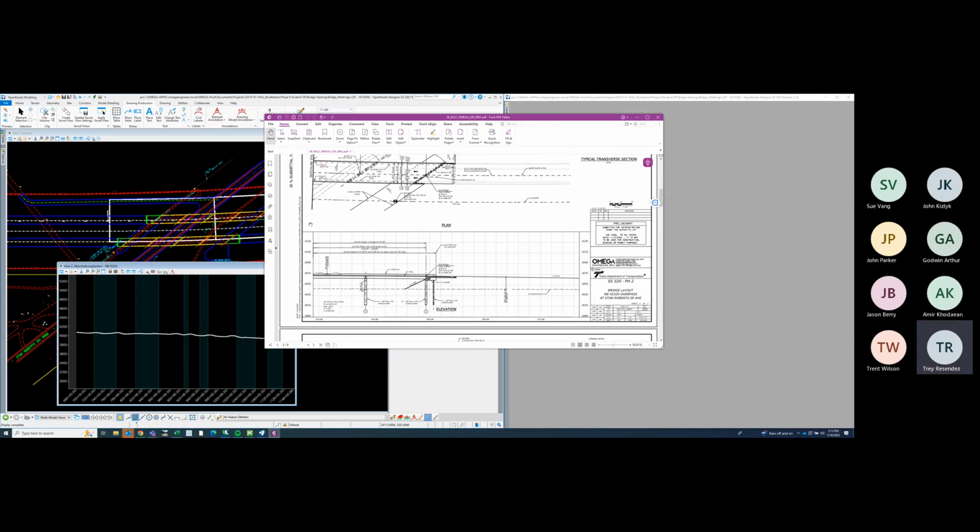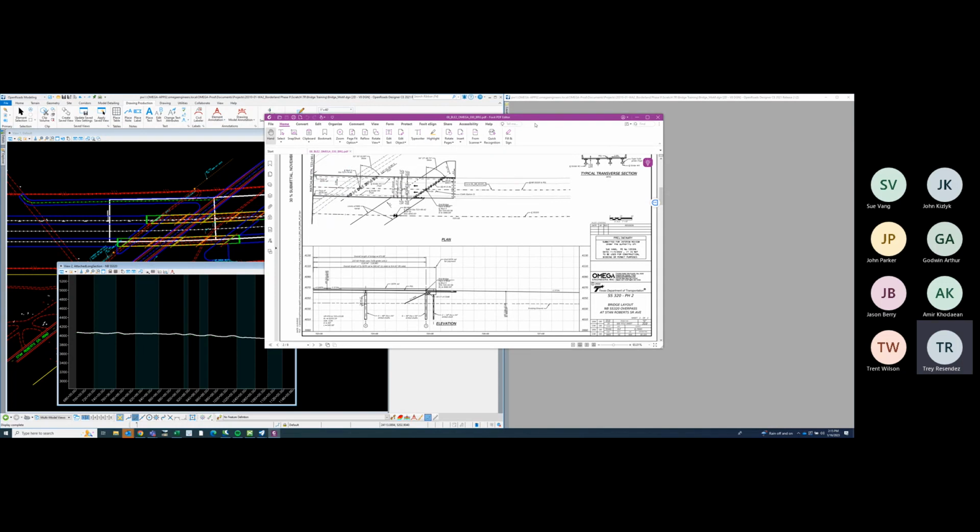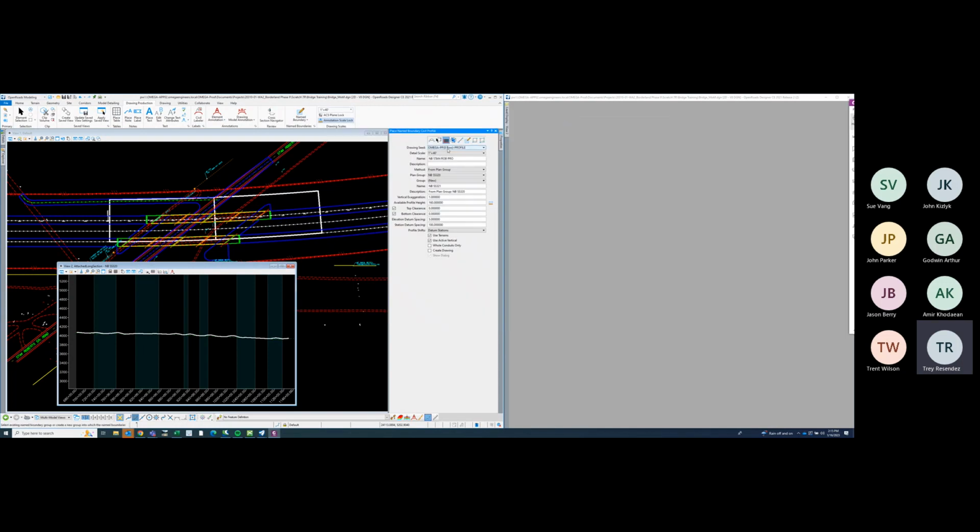And if you notice here, this says 8 row for the name boundary setting. And all that means is there's 8 rows for your profile to show. So just keep that in mind. If you ever need a couple more, we do have settings for 10 rows, but for this example, we'll use 8 rows. And we'll choose the scale.